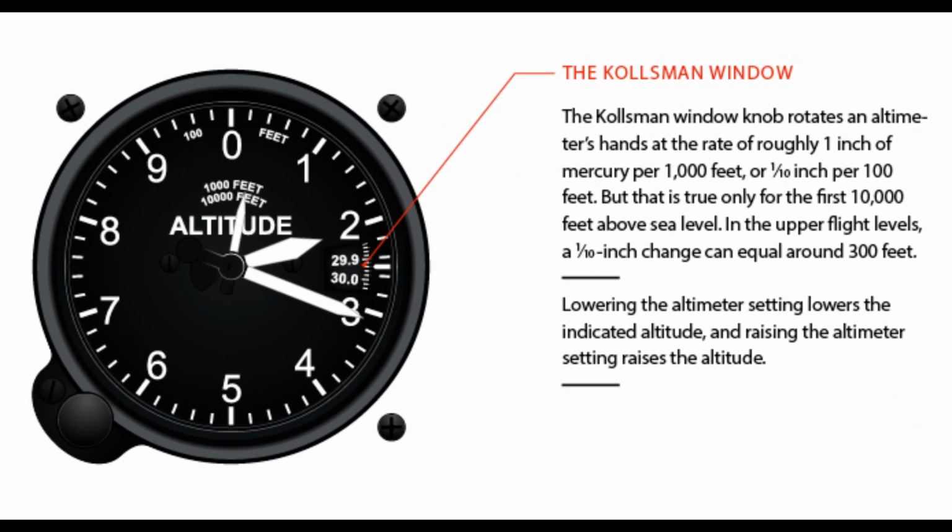Barometric pressure for standard altimeter setting, QNE. Use the altimeter setting, en route, at or above the transition altitude, FL 180, in the United States. The altimeter setting is always 29.92 inches of mercury / 1013.2 HPA for a QNE altitude. Transition levels differ from country to country and pilots should be particularly alert when making a climb or descent in a foreign area.